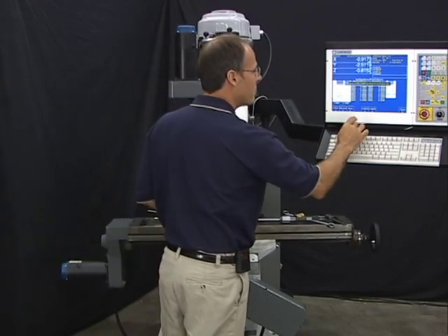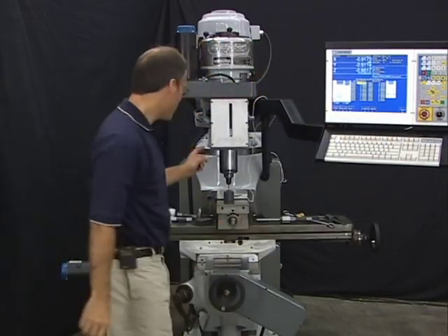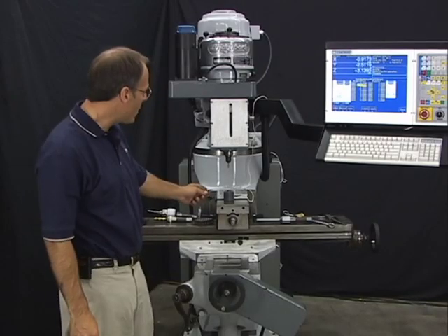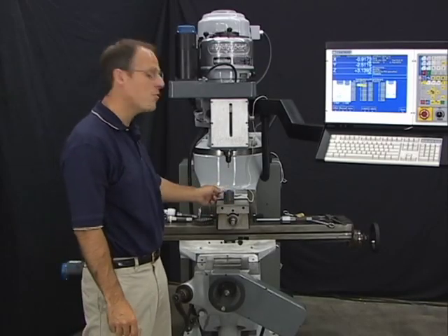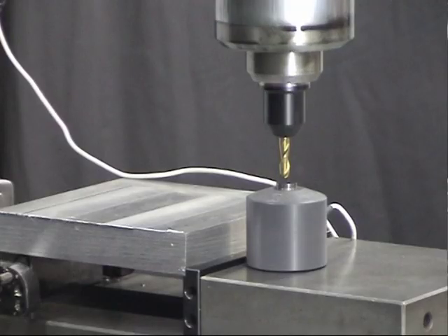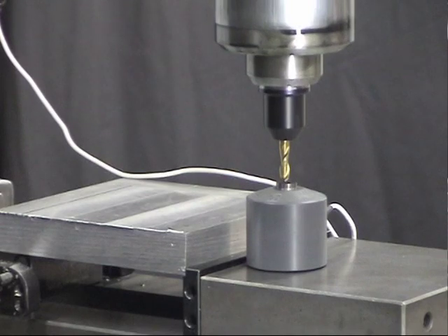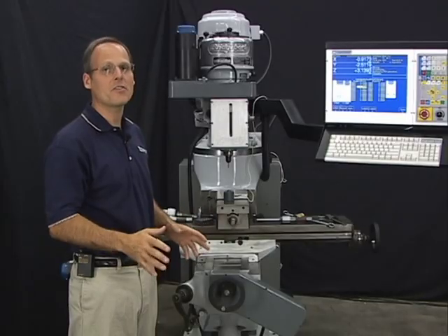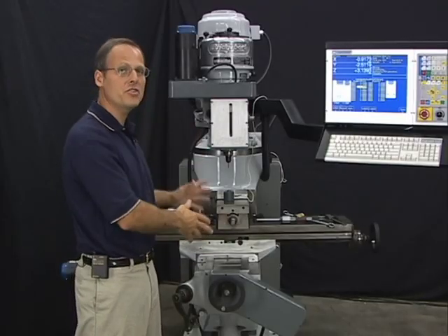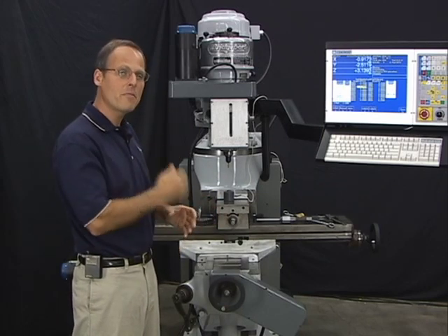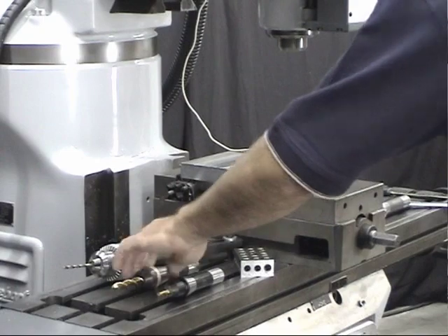Now I can hit F3 auto, then cycle start. The tool automatically comes down, touches off the probe. If you're watching real close, you'll notice that it hits the probe once at a fast jog rate, backs up a little bit, and then slowly comes in and touches it. That's to achieve maximum accuracy. The TT1 is as good as your machine. If your machine's holding tenths, you'll be able to repeat tenths on measuring tools. Now let's load the next tool.